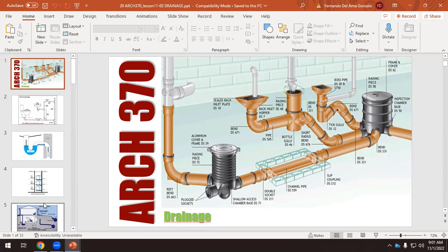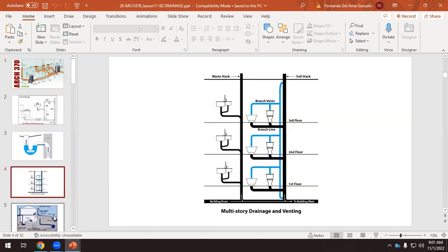when we have drainage or a sanitary system, we have a stack that goes down, but we have a vent that goes up. Okay, and without that vent, that can't work. So that's the first thing that you have to keep in mind. We all understand that it has to go down, but remember that it has to go up because the air has to enter this, and it's the air that is moving the water all the way.